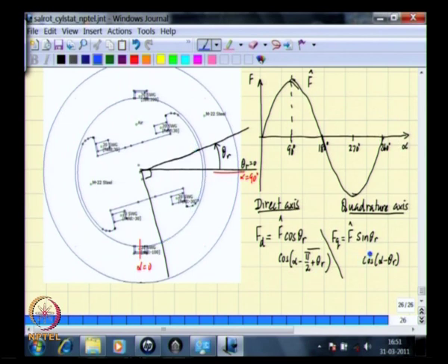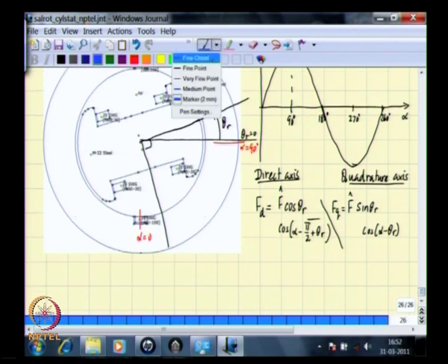This expression describes the stator MMF resolved along the interpolar axis and distributed sinusoidally around the inner circumference. If these two represent the original stator MMF resolved into two components, then it also stands to reason that if you add these two, you get the original distribution back. Do we get that? Let us try to add these two terms.